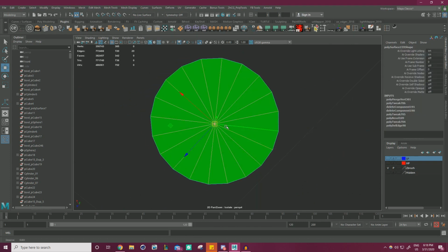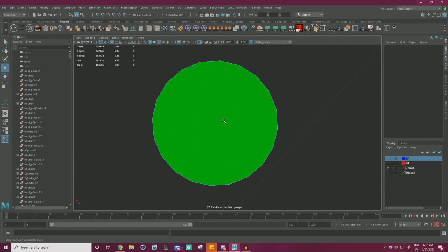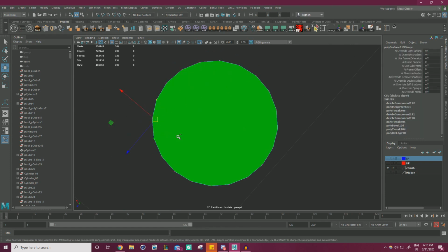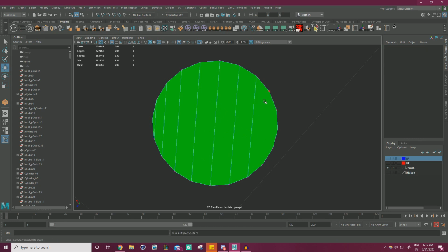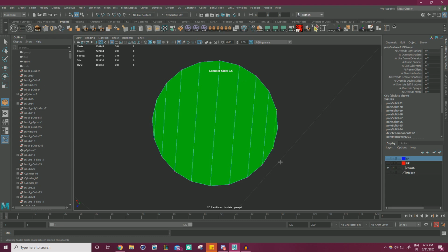If we really want the lowest poly count possible, what we can do is connect the ends like this. When you're trying to get the lowest poly count with a cylinder, this will actually get a lot less than if you were to have everything merging in the middle. Not a lot less, but it'll save you a few polygons, and since we're duplicating this around, we might as well save as much geo as we can.